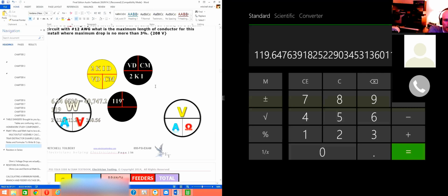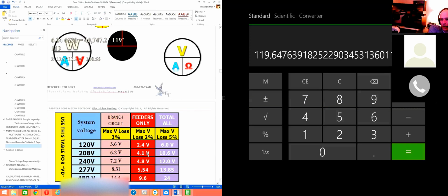And so those two formulas right here, and then this chart right here, used to be you could put them on page 766, because there was a little bit of room there next to that table 8, but now there's not. There's a little bit of space under table 5A, which is just there, I think, to the left of table 8, isn't it? Yeah, table 5. See that space on the bottom of page 765? Yep, exactly. So I'd put those two, the two kids on the block and then the mirror image of it and that little table right there. I'd put those on this page and then my notes to copper being 25.8, aluminum being 42.4, and again those being single phase copper, single phase aluminum.